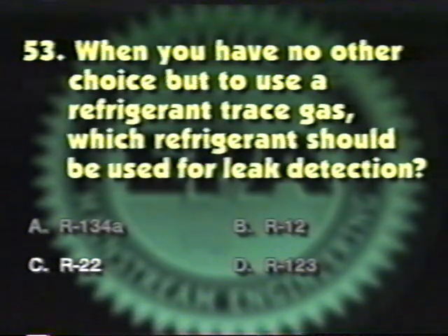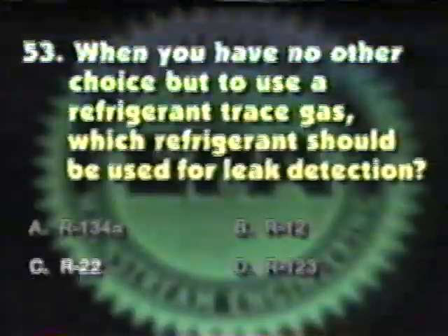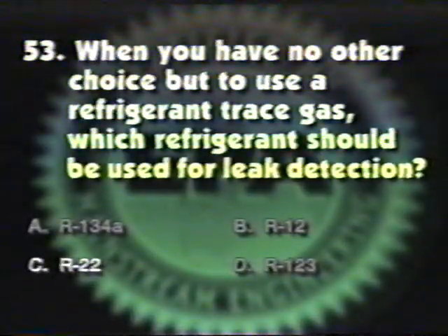Also, it is not legal to avoid refrigerant recovery by simply adding nitrogen to a leaking R22 system and then calling the charge a leak check gas, which need not be recovered. Rather, the system must be evacuated first, repairs made, and checked for leaks with nitrogen. At that time, if a leak is detected and an electronic refrigerant detector is to be used, then it can be charged with a small amount of R22 and pressurized with nitrogen to locate the leak.